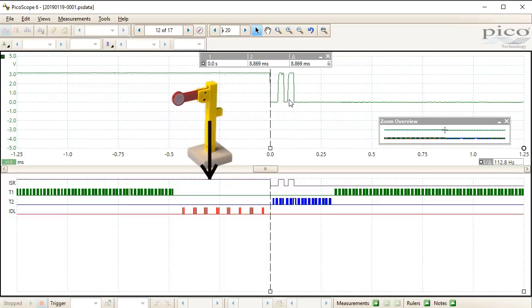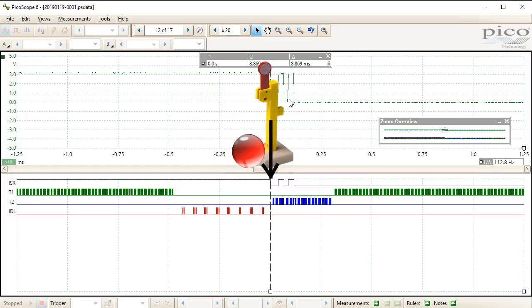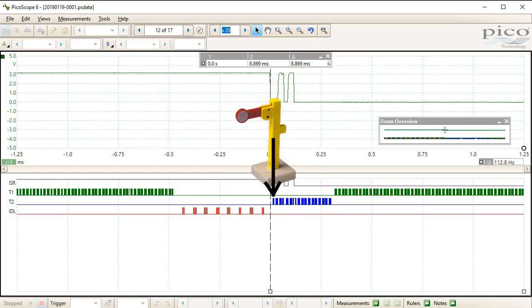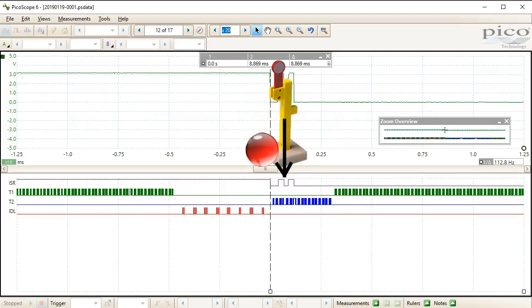Before the switch was pressed, the semaphore had no tokens, so the Blinky2 thread blocked on the semaphore wait operation. The first falling edge caused the GPIO interrupt to signal the semaphore, which added 1 token. This has immediately unblocked the Blinky2 thread, which, still inside the wait operation, took the token out of the semaphore. The next bounce caused the GPIO ISR to signal the semaphore, which again added 1 token to the empty semaphore. But this time the Blinky2 thread was already running and didn't yet execute the semaphore wait operation to remove the token, so the token stayed in the semaphore.